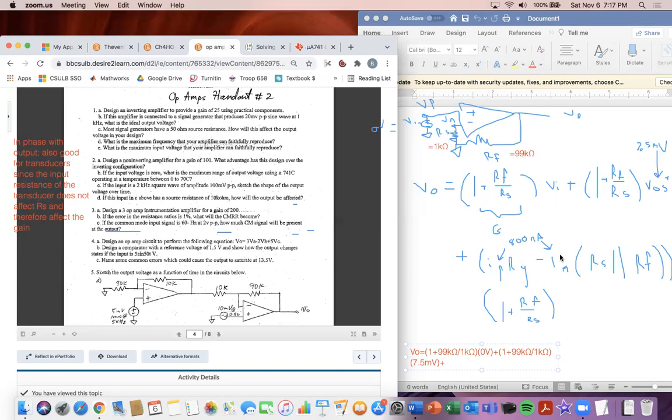But if you still have that, that would still affect the negative here. So I P, which is 800 nanoamps. They never gave us an actual one for the source resistor. So that would just be 0 minus, and then I of N, which is 800 nanoamps from that data sheet. And then the parallel is 99K ohms in parallel with 1K ohm. And then multiply that by the gain finally. And so the gain would be 1 plus 99K ohms divided by 1K ohms. And then you'll get your output voltage.